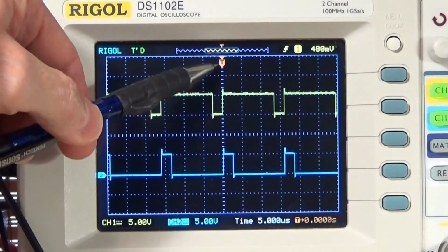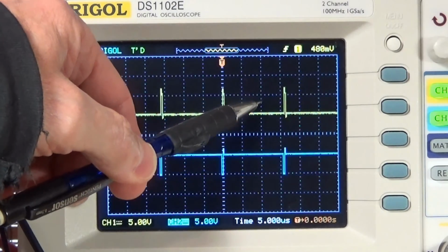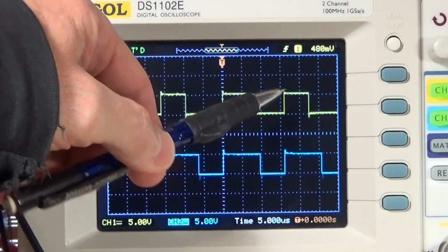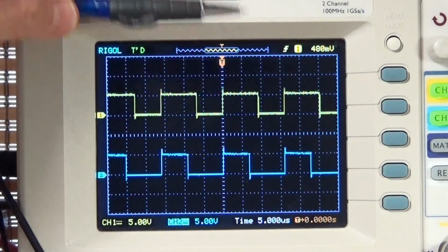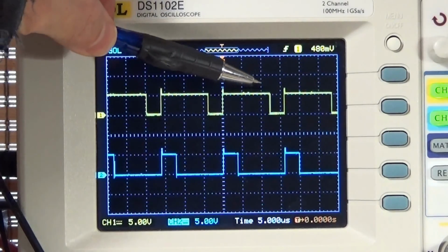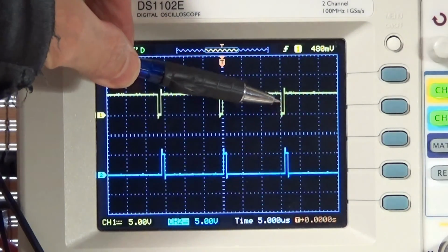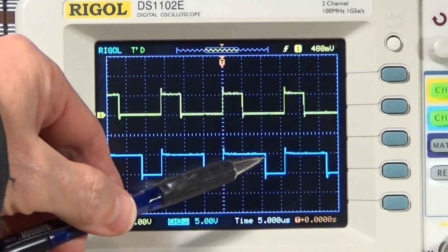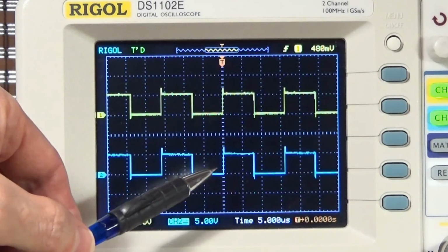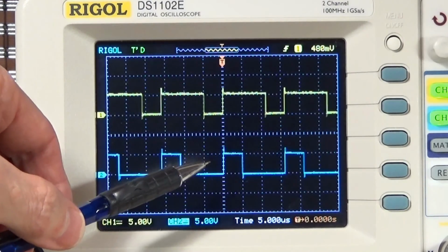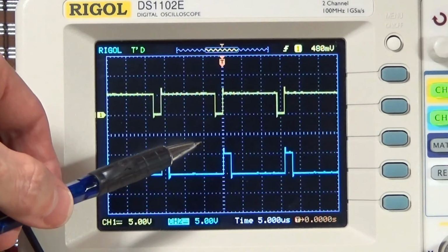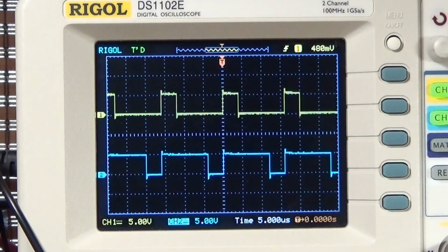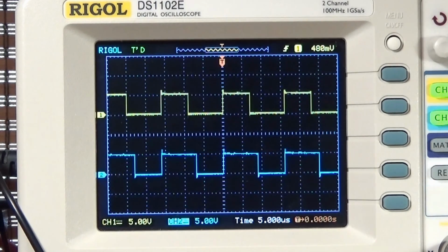So if you look starting at the trigger point here, you can see how the duty cycle in this one is increasing. Starts at 0 and then it's increasing, getting bigger and bigger, and eventually it reaches maximum duty cycle where the line is high. And we'll see here in a moment when this almost goes away and it's high for a moment and then it switches over. And we'll look at the other one, which I had a decreasing duty cycle, so you can see how this high point is getting smaller and smaller. If I were to hook these up to 2 LEDs, then you will see the 2 LEDs changing in intensity. So that's what the varying fast PWM signals look like.